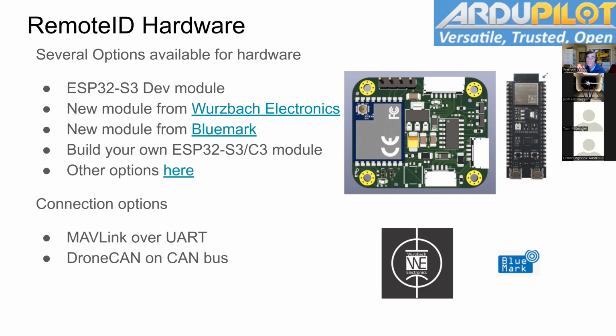So you basically have Mission Planner running on your phone, talking over Wi-Fi to a TX mod in your Tyrannus, that communicates with the vehicle, and that then provides all the Open Drone ID messages from your phone via the TX mod over the RFD 900X 900 megahertz link to the vehicle, out to the transmitter module, and you're good to go. I would expect that would work, but I haven't yet demonstrated that end to end. I did the first flight with ArduPilot Open Drone ID on Sunday, so this is all very new. But that's where I think it would be heading. Does that make sense?